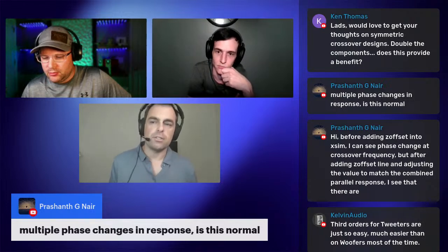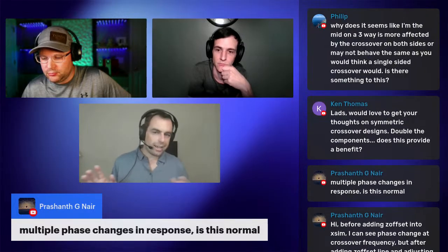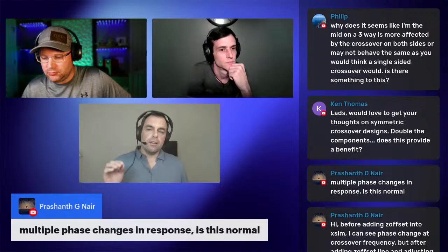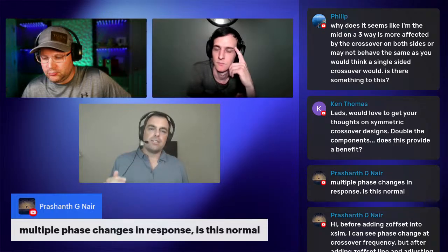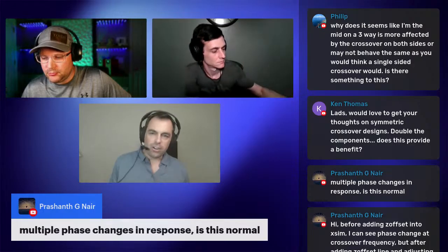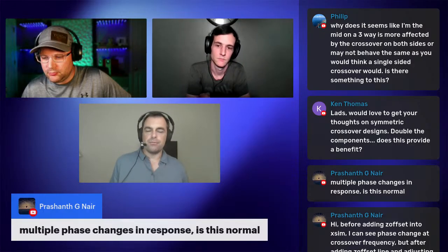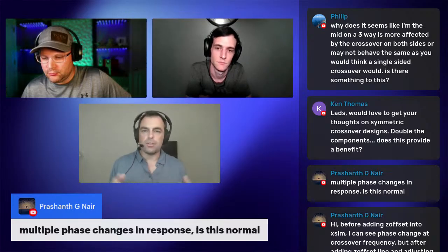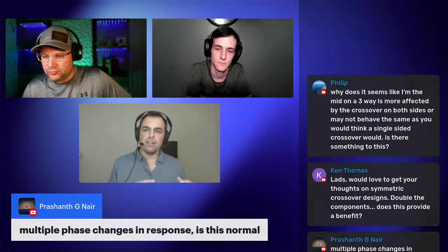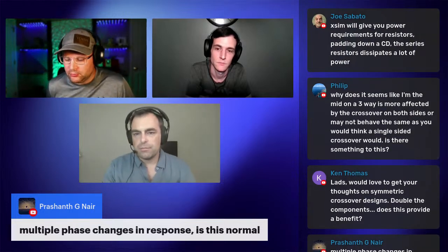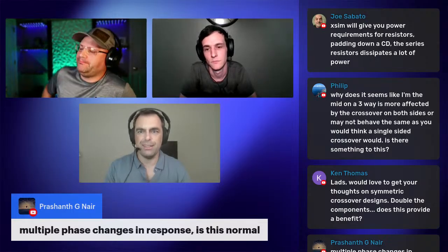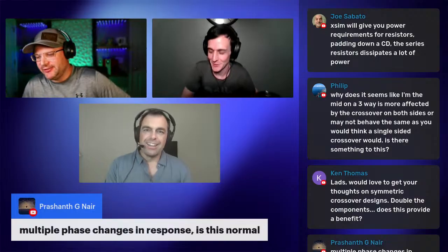I got to say something about phase, because phase is really tricky. We're not going to get into phase and why it happens and what to do about it and everything. But can I just say, people make way too big of a deal out of it. The reality is, getting your frequency response right, getting your off-axis response right and everything far exceeds the sonic qualities of trying to get as little phase shift as possible or anything like that. You're talking about in the crossover region? Yeah, exactly. Like whatever you got to do. I mean, I've heard of people like, oh, I wouldn't use that notch filter because it introduces phase. I'm like, but there's a 6 dB peak in the response that I got. Which one do you care more about?